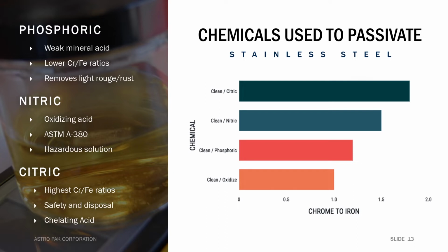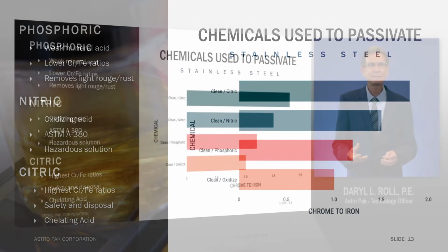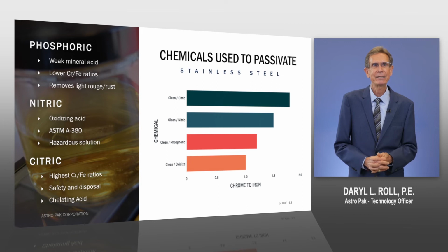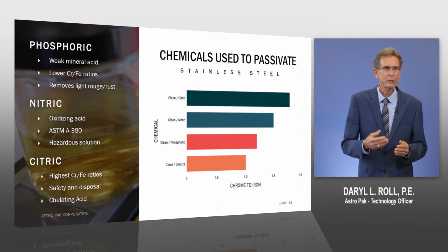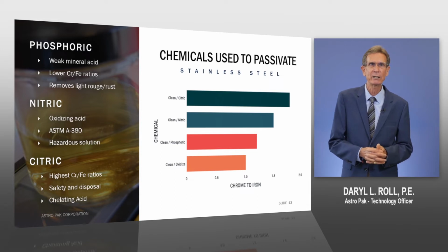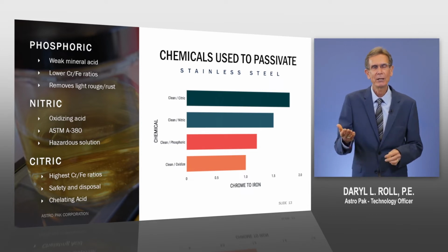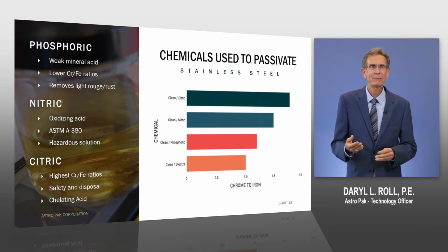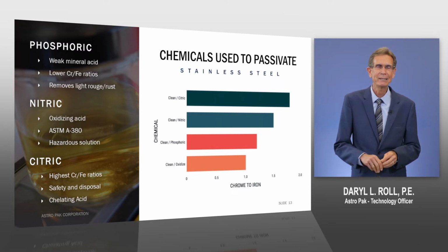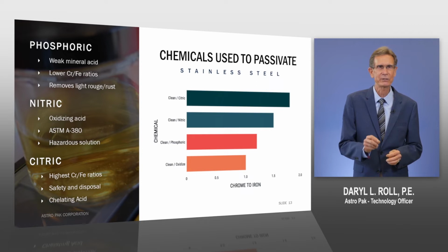film that we receive. As a guide, the quality of the passive film is based on the chromium content, but we also do corrosion rate testing. And just to give you an idea, the difference between a surface that has a 1 to 1.2 chrome to iron ratio when compared to the level of nitric at 1.5, nitric has approximately 2 times the corrosion resistance.